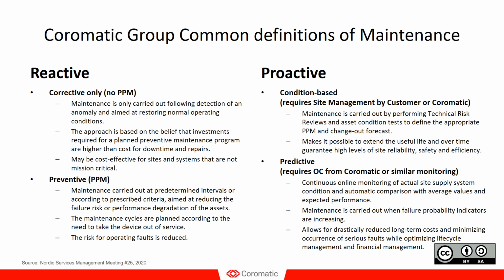For example, having test cycles at a given interval or replacing components at a regular interval, regardless if they are in a good condition or a bad condition, they need to be replaced within a certain schedule. That means you lower the risk of having to perform corrective maintenance at high cost and with no planning. On the other hand, you still need to have corrective maintenance in case there is a problem or an incident.